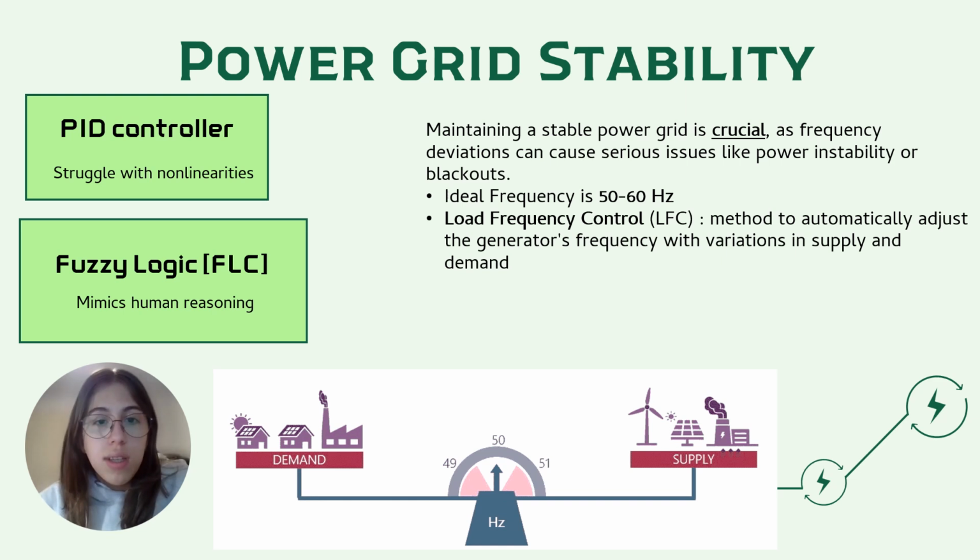So LFC, load frequency control, is a method that automatically adjusts the generator output to respond to these variations in order to maintain balance. Traditionally, PID controllers are what we have used for LFC, but they do have limitations because they have fixed parameters, and they struggle with nonlinear system behavior.